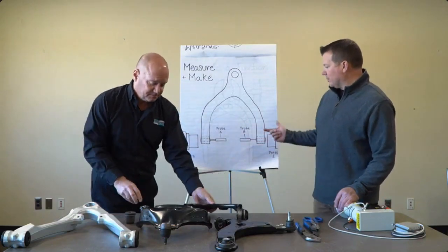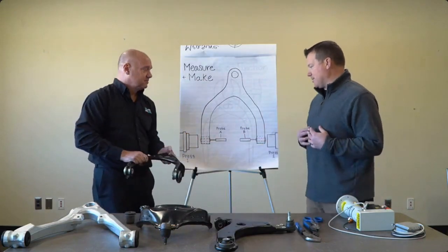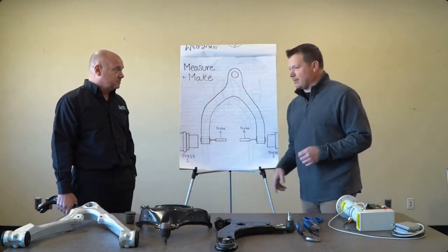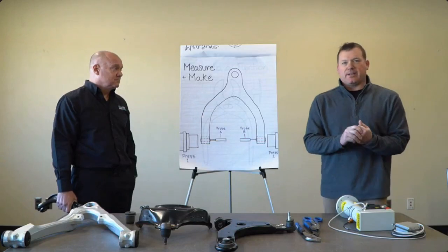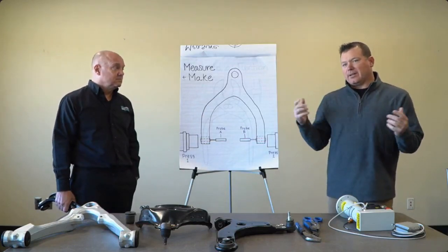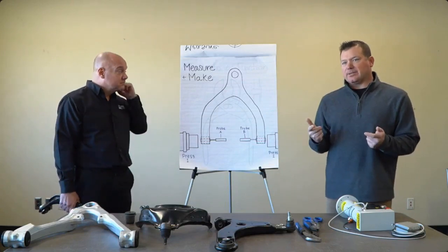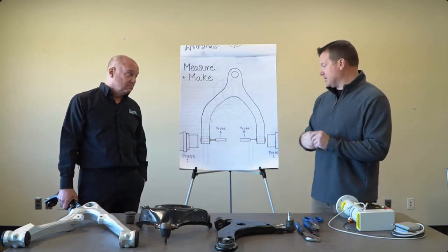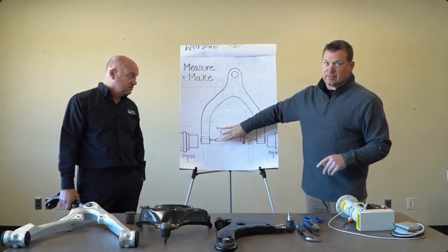What makes it simple from our aspect is that we can simply take these probes into our system, and we have canned routines that are parameterized. So you're literally just entering in values. The system calculates what needs to happen, and then it adjusts. And it's a servo system, so it's very precise. Measuring probes have accuracies of a micron.